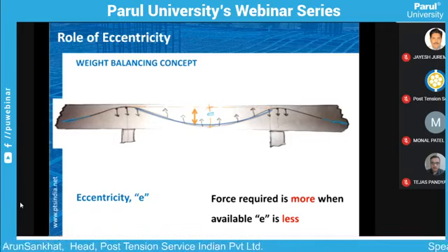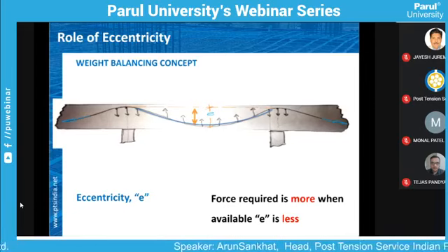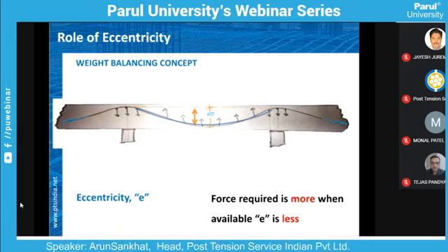There are factors to be applied if we need to increase the span, and accordingly we have to at least start with those depth values by comparing with the span by D ratios. So for a specific span, that minimum depth is required,